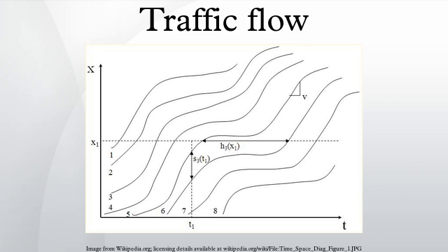The F→S phase transition in metastable free flow at a highway bottleneck does explain the empirical evidence of the induced transition from free flow to synchronized flow together with the flow rate dependence of the breakdown probability. In accordance with the classical book by Kuhn, this shows the incommensurability of three-phase theory and the classical traffic flow theories. The term incommensurability was introduced by Kuhn in his classical book to explain a paradigm shift in a scientific field. It must also be noted that the existence of these two traffic phases, free flow and synchronized flow, at the same flow rate does not result from the stochastic nature of traffic.